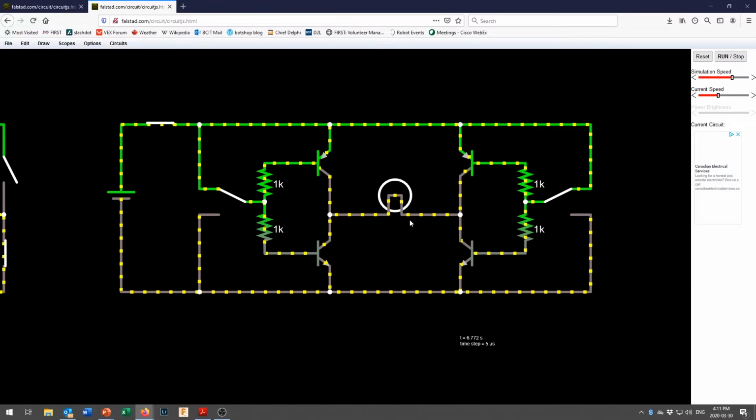And that inductive magnetic field around the motors, I like to picture it as like the electricity being like a freight train. When you get a freight train moving, it takes a little while to stop it. So picture this as a big freight train coming through here, and somebody suddenly trying to slam on the brakes. Well, if you put a brick wall in front of a freight train, you're going to have a bad day. And you're going to have some energy spikes when that freight train hits that brick wall. And that's what we're doing right here when we're suddenly turning this off.